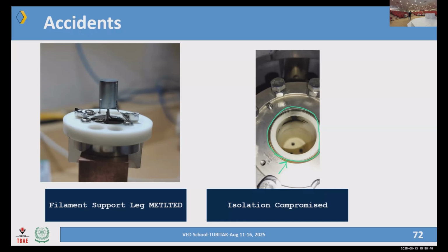Sometimes we want to sleep. We rest our head on some support. So this cathode was touching the focusing electrode, and the hot spot was created, and that hot spot was not very well cooled, because this was at 1000 plus degrees Celsius. This couldn't handle it. Excellent. We came to the same conclusion.